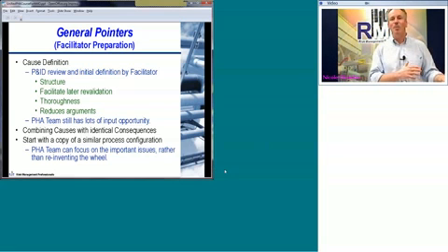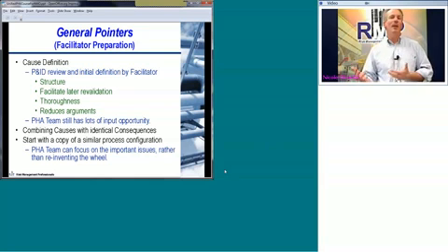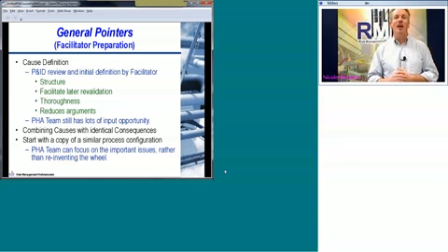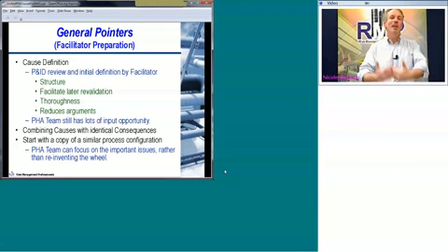They spent a lot of time discussing under what process deviation a failure would be, and if you've already got a structure that works, and the team says, well, wait a second, what about this high temperature issue? You can say, we've already got it logged as a causal event that we're going to be looking at, and it immediately curtails the discussion to get them back on track so they can be thinking of new scenarios. But it doesn't want to stifle their thinking about it.